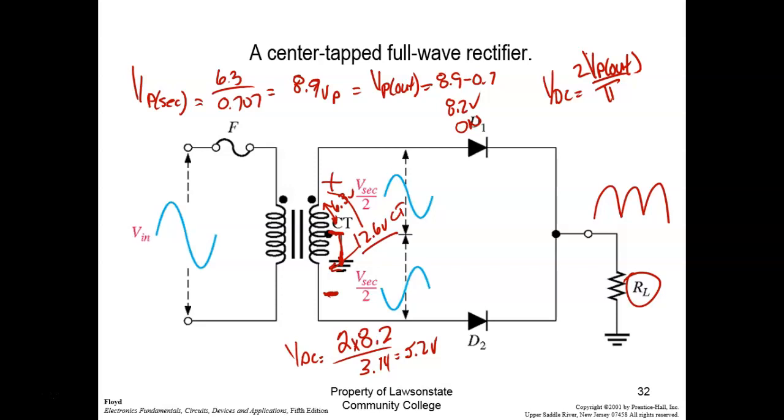But when you buy the center tap transformer, you don't buy it as a 6.3 center tap. You buy it as a 12.6. That's what I don't like about the trainer, because they show you the 6.3, but if you took the transformer out, it's going to say 12.6 center tap. And I go try to find one of these transformers for you. So it's rated at the full voltage, but we're only using 1/2 of that at any one time, right? Does that make sense? Right?